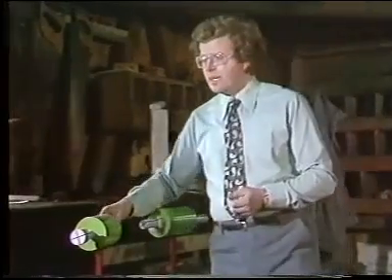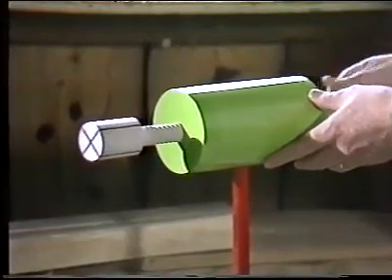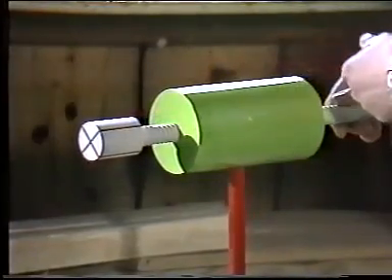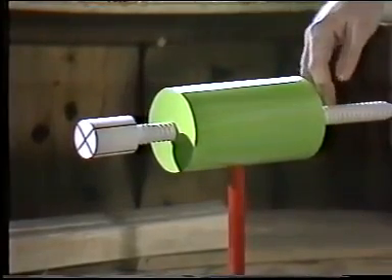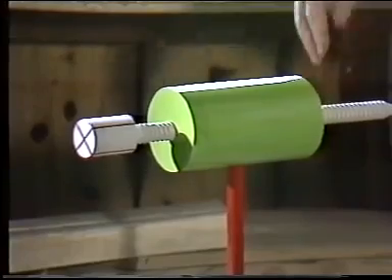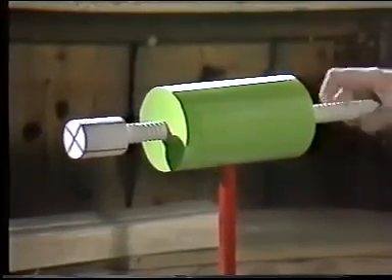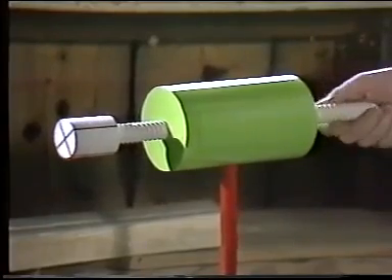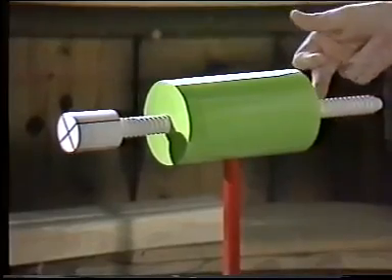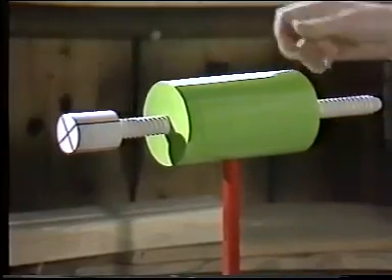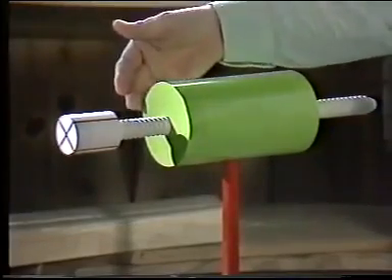The third one is the screw pair. Now that allows me both a turning motion and a translational motion. But the two are linked together. They're linked by the pitch of the screw threads, that is the angle at which these threads are cut. And therefore, really, there's only one motion possible there as well. And I need only one parameter to specify the position of one link relative to the other. This can be either the amount I've turned it or the amount of translation.